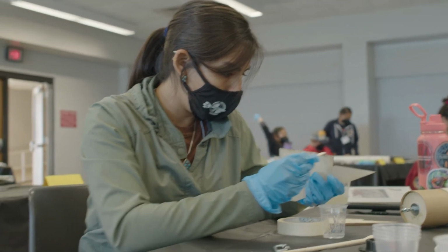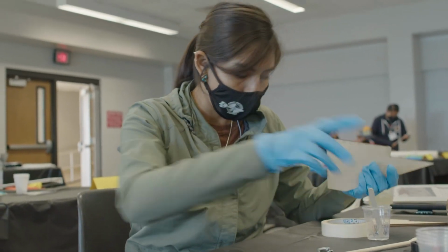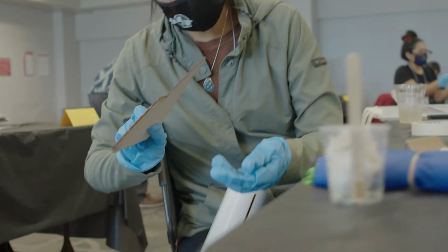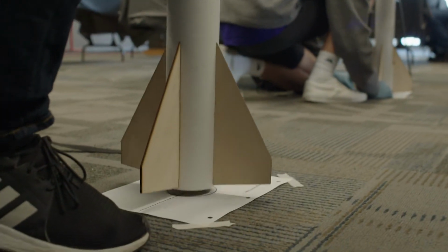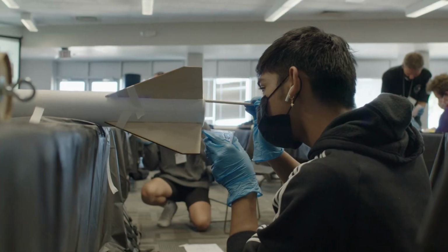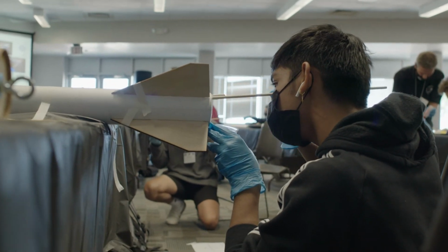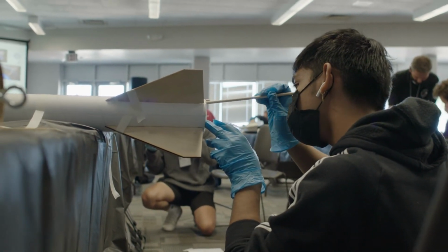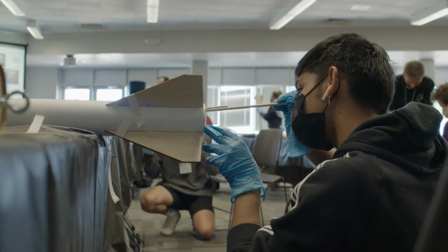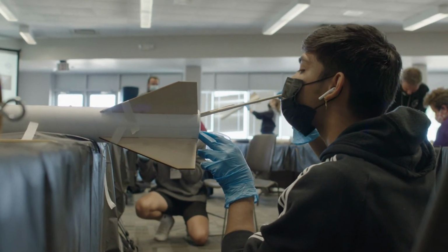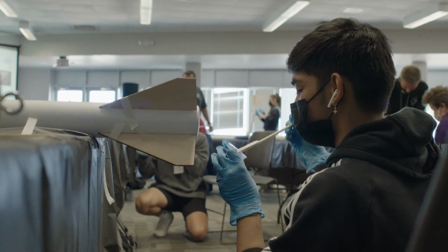Another common challenge is applying adhesives to the inside of the airframe tube. High-stress components like centering rings and rail buttons will require solid bonding and possibly backing to ensure structural integrity. One common trick is to use a rounded dowel as a long-reach applicator. For critical placement, you can mark distances along the dowel. There are also brushes and applicator syringes available commercially, and sometimes it is just the team member with the longest or thinnest arms.